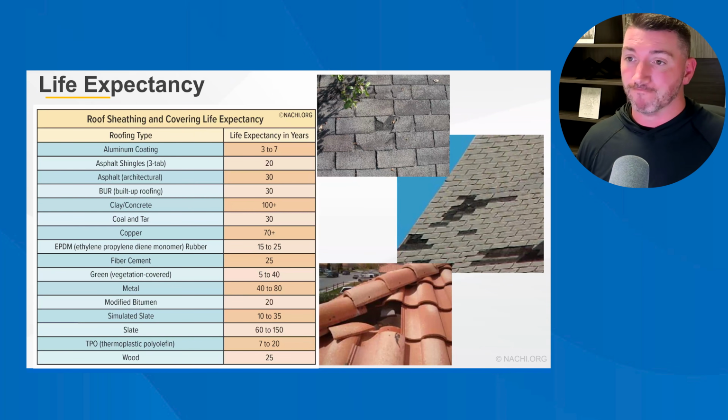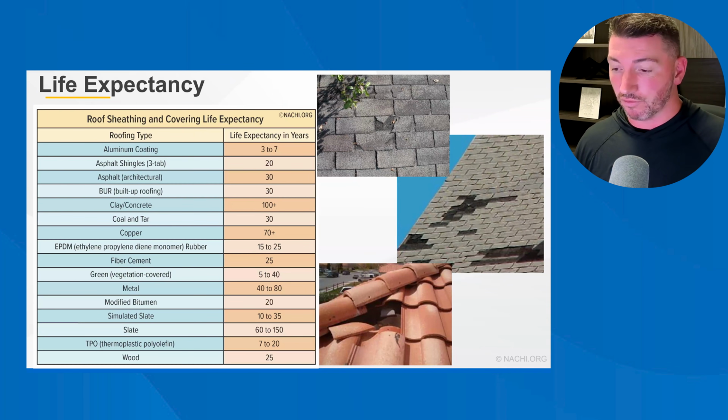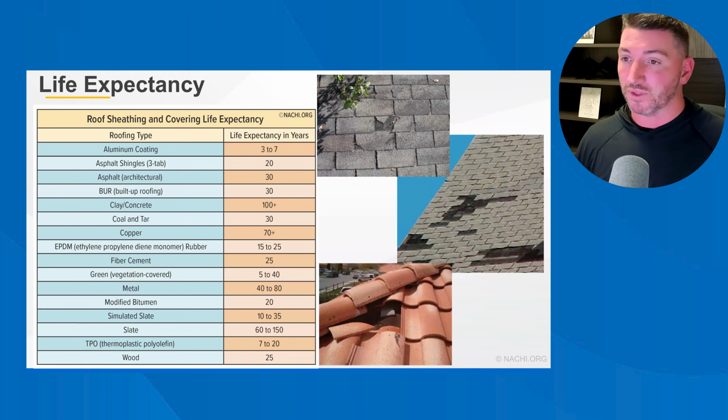UV reflecting component of the shingle, right? The water shedding medium is the asphalt, and the granules are there to protect the asphalt from breaking down from the sun. So if you have algae building up on the surface, don't let these soft wash guys tell you that you're preserving the life of your roof by washing the algae off.